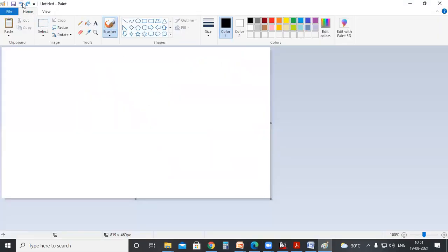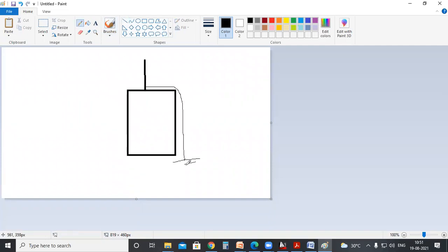So this one is our building. You have provided the lightning arrestor, and this one is safely earthed to the pit. So whenever lightning strikes your building, it will be discharged safely, so nothing will happen to your building. In that way, you can directly protect your building. It means you can protect your equipments from direct lightning strikes, since your whole building is being protected from the lightning strikes.